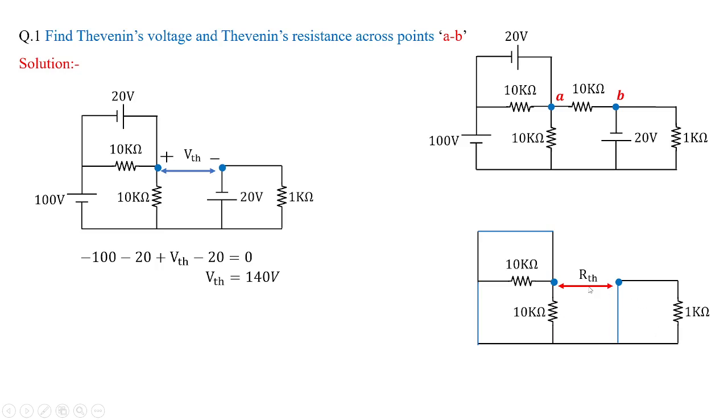So hence on the right hand side and the left hand side, by looking into this particular network, we are going to get the resistance value as 0 because the voltages are replaced by short wires. Hence the current is going to flow in this short wire compared to the resistance. In resistance, the parameter is overshadowed by the short circuit. So hence the overall resistance of this particular circuit, when you are looking through terminals AB, is 0. So the Thevenin's resistance is 0 ohms here.